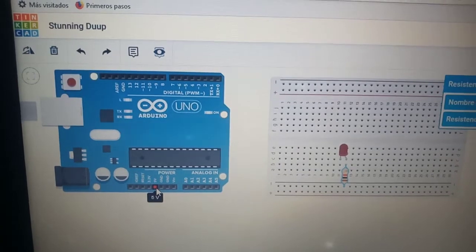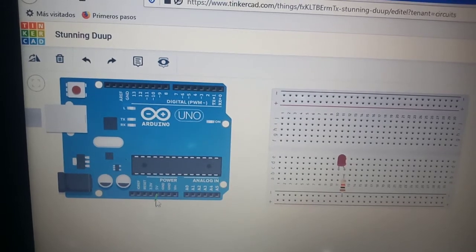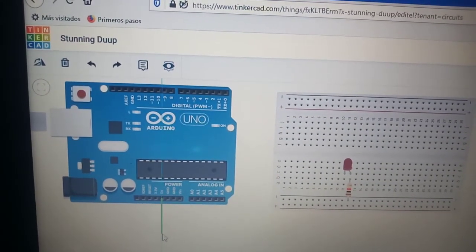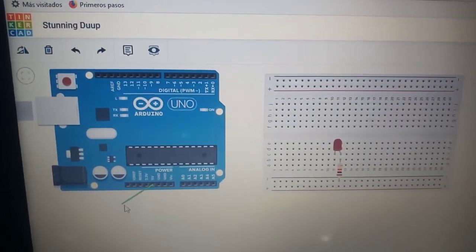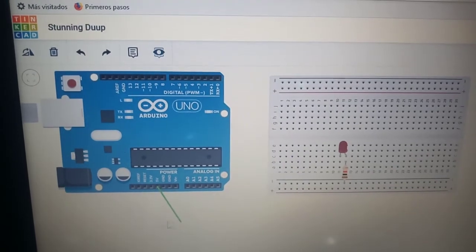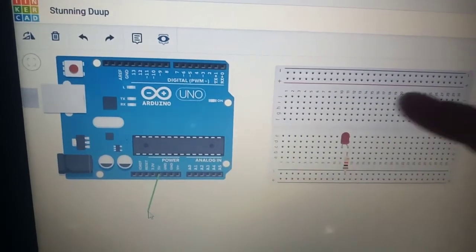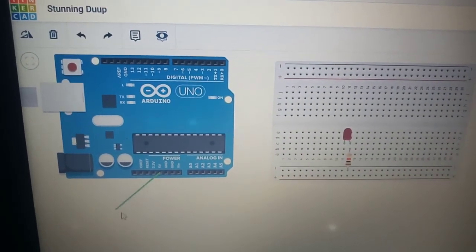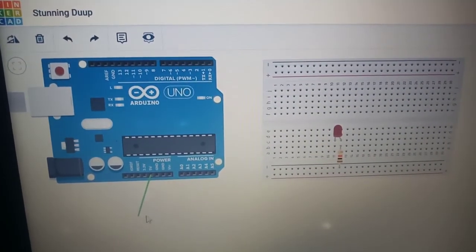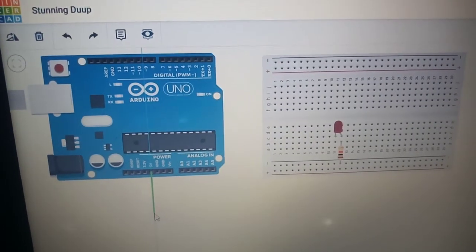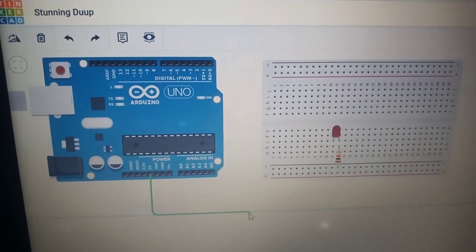5 volts is a positive voltage, so we're going to click on this box, and as you can see, what will be called a wire automatically comes out from that box, and I can move it in whatever direction I want. I just clicked once on that box. I'm not keeping the click pressed, so the movement of the wire is free. I have to click again if I want to turn the wire in any direction I want.